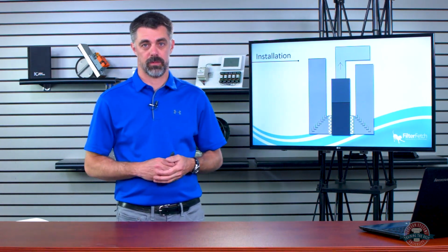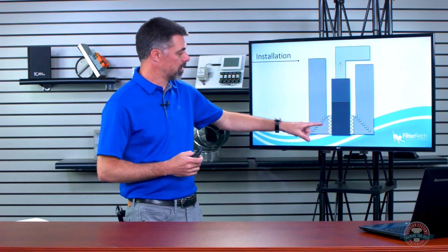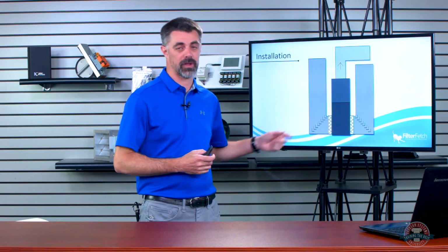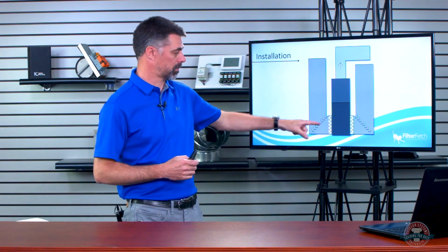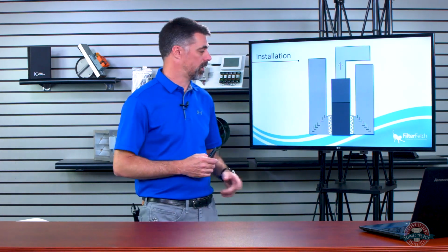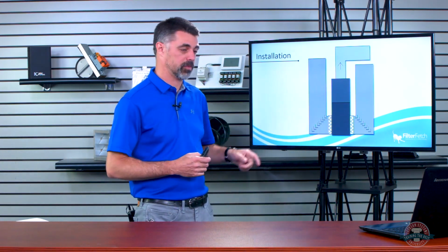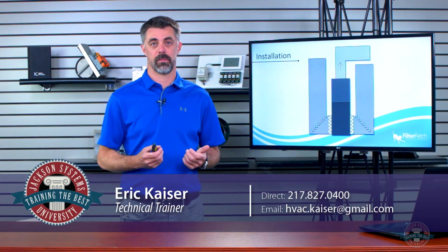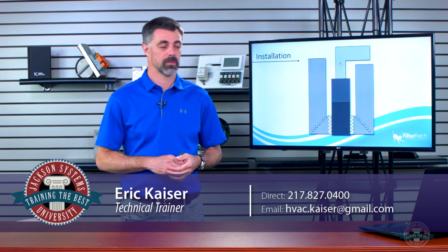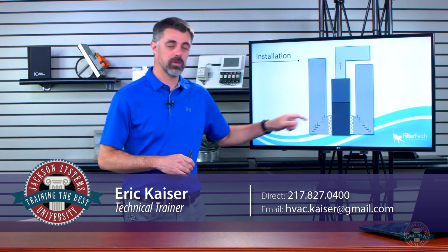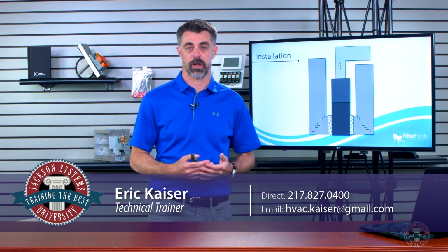Now, if you need more airflow, quite often, manufacturers, when you get up in larger tonnage in residential, light commercial, unitary equipment like this, you need to feed either from the bottom, or we need to feed from both sides of the blower compartment, bottom or both sides. And so we can feed from both sides like this, because remember, if we go back to that pressure drop chart, and we're using even that 2-inch filter, a 20 by 25 will run about 1,000 CFM, a little bit over. So we're going to need two of those 20 by 25s in order to get a low enough pressure drop.